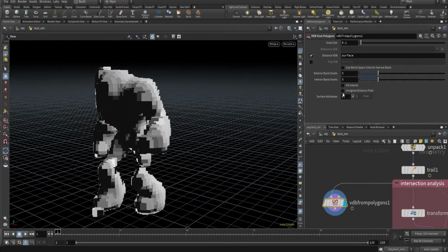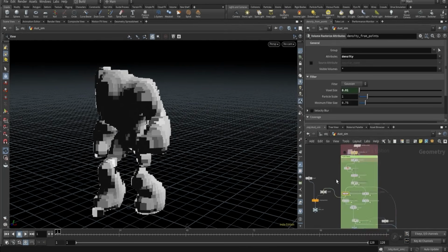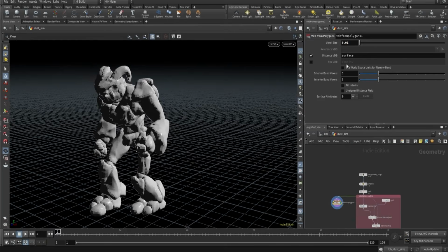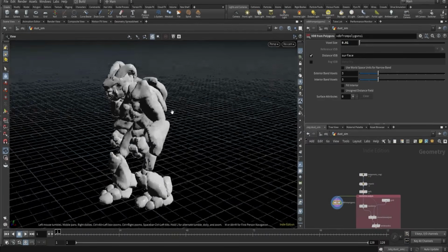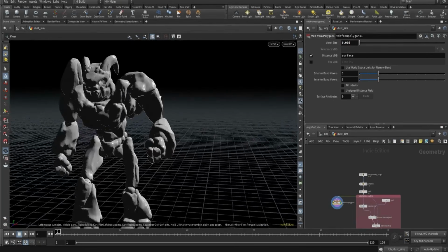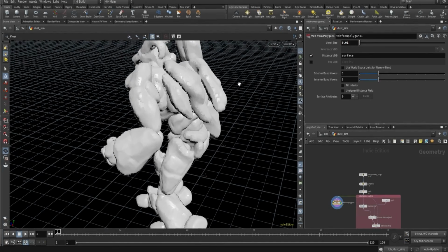And we can link this parameter with the voxel size here as well. But we don't want to link that. Here a decent voxel size is also fine, but if we increase the simulation voxel, then we don't require this kind of detailing. It's better to keep this independent, right? So we don't need that high quality voxels over here.